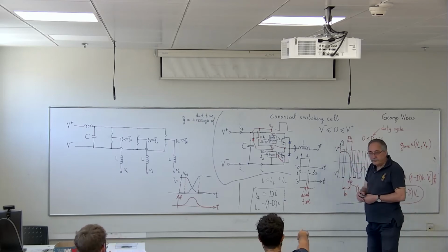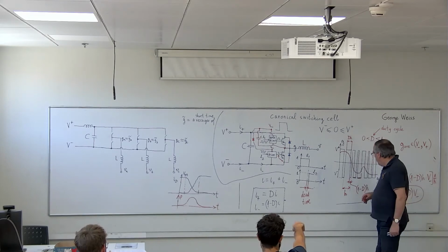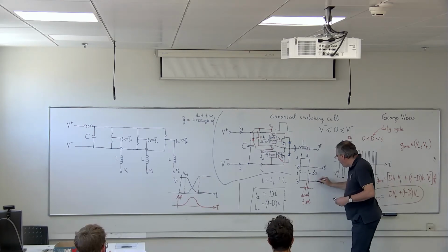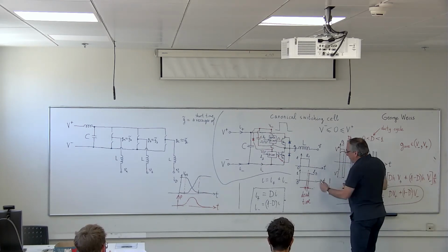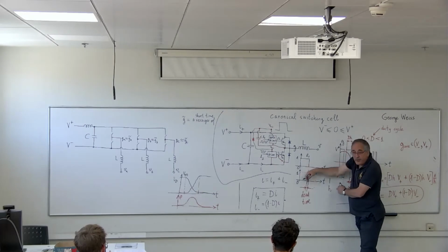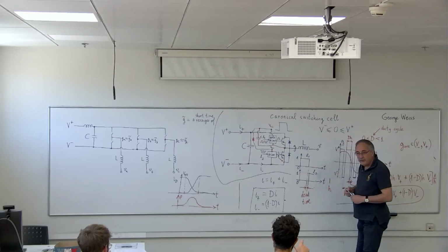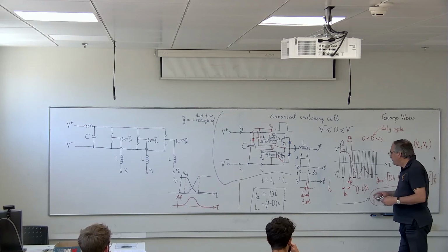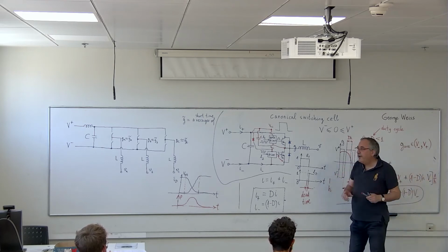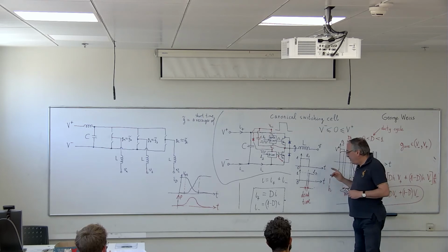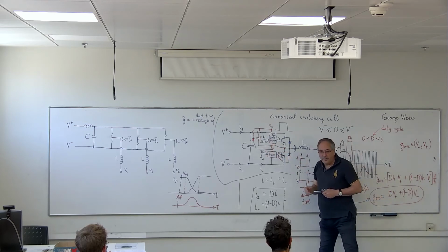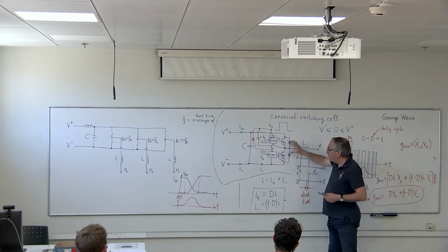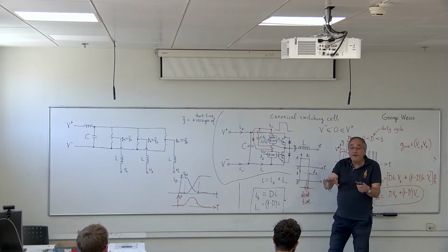So it's that part of H, the H that we have there. Oh, this dead time happens within all this H, right? Yeah. H is much longer. H is, let's say, here. So this happens within one switching period. Yes. So you don't really have DH and 1 minus DH, but you have the dead time. You have the dead time in the PWM signal. Okay. But with respect to which part is conducting, the upper or the lower, you do not have a dead time.